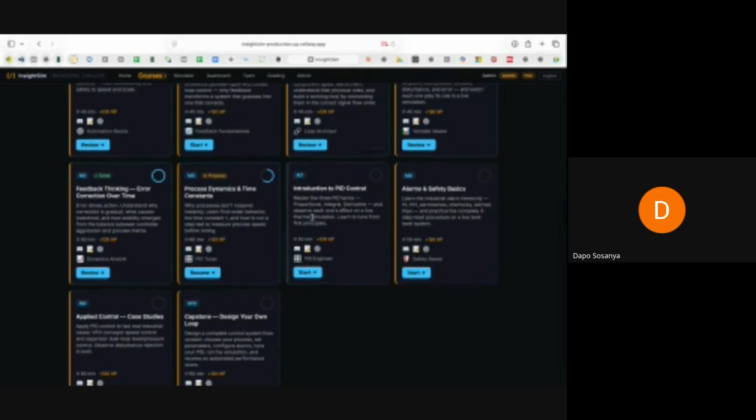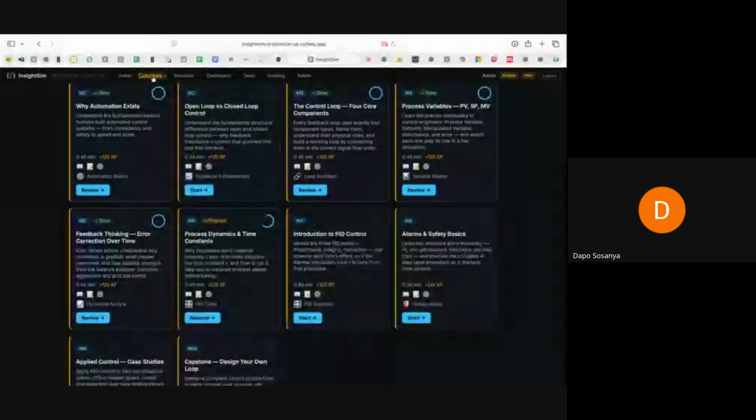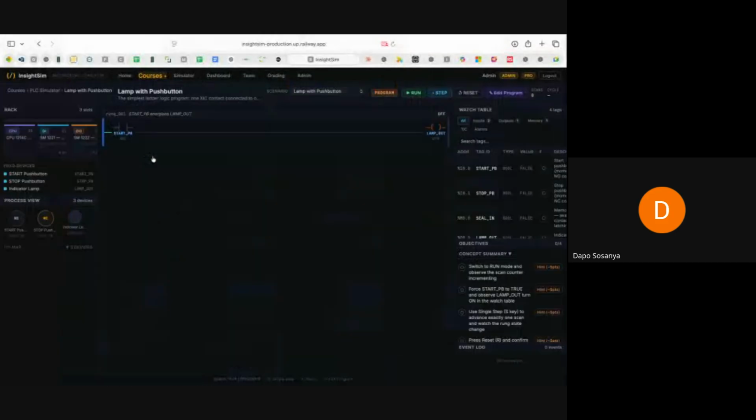One of the strengths of this simulator, again, is that with the PLC simulator you can simulate the effect of the process time constants on the PLC, and you can see. That's why we measure the scan here. So you can do that scientific measurement, factor in the time constants, measure it, and see the effect. And it helps you to be a better PLC programmer.